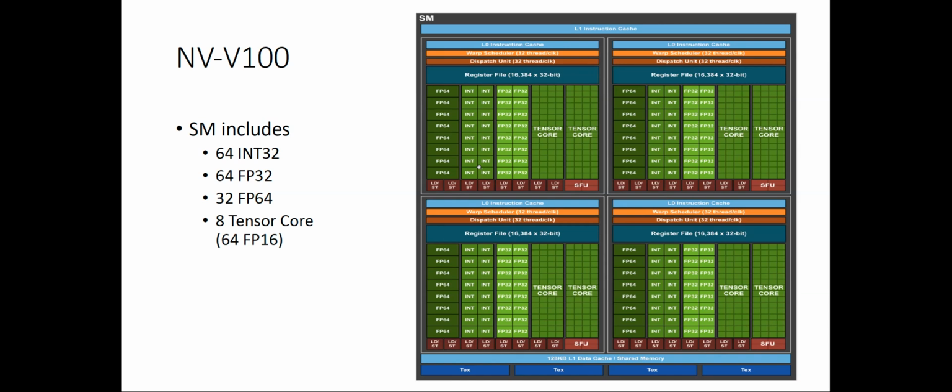Floating point 32 has an 8-bit exponent part and a 23-bit mantissa part, while floating point 16 has 5 bits of exponent part and only 10 bits of mantissa part. So they have a different distribution, but FP16 still gives very good accuracy and training performance. That's why we adopted this new tensor core unit within this ASIC core, just to accelerate this data type and provide extremely high computation intensity.